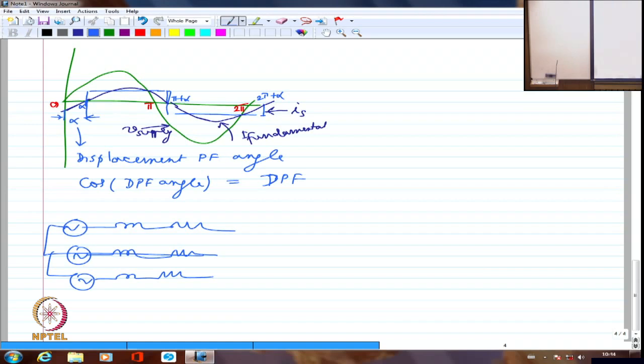So although I generated a sinusoid, now I am going to have some harmonic voltages, maybe negative, maybe positive, whatever, that is generated in the transmission lines, which is ultimately going to reach the motors and so on, which I am connecting in the power grid.